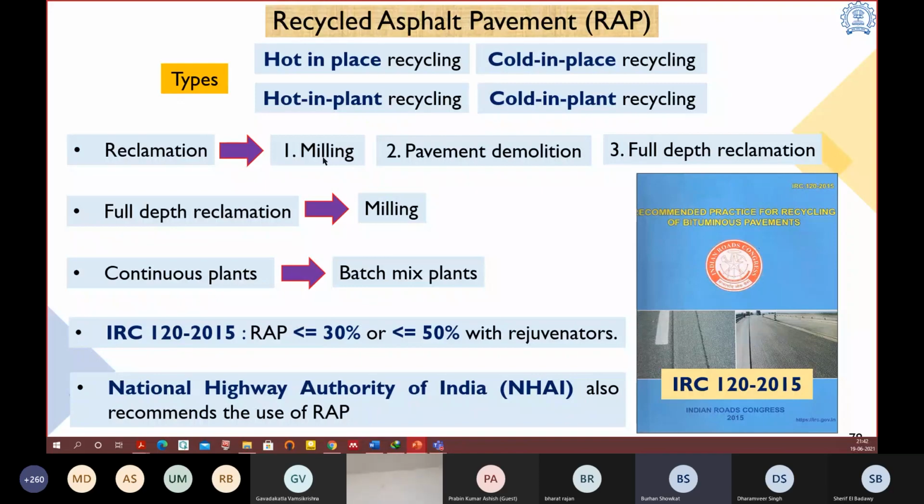As far as the economic reasons are concerned, RAP enables us to utilize the bitumen that already exists in the RAP. Thereby, it leads to a reduction in the expensive virgin bitumen. Therefore, the large quantities of RAP generated during maintenance and construction operations can be utilized for the construction of pavements.